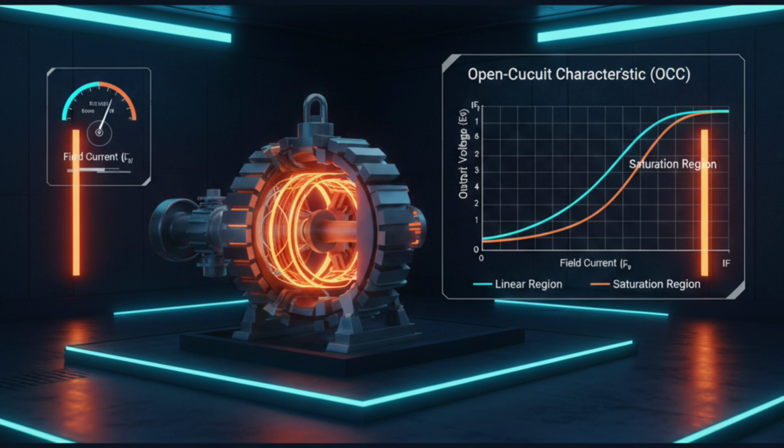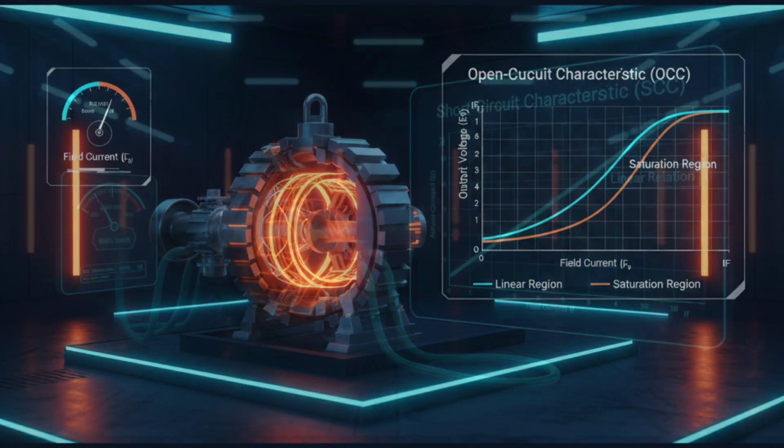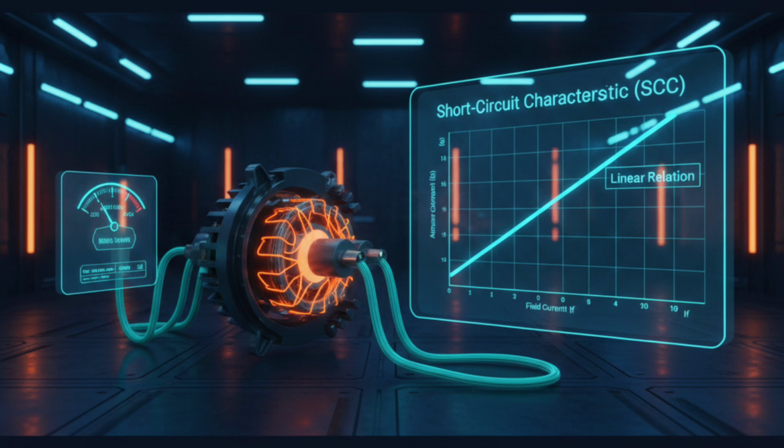Marine engineers refer to this curve when setting AVR control ranges and excitation ceilings. OCC is also used during calculations of synchronous reactance and voltage regulation. In examinations, you should be able to explain why the curve becomes nonlinear and what saturation means physically inside the alternator.